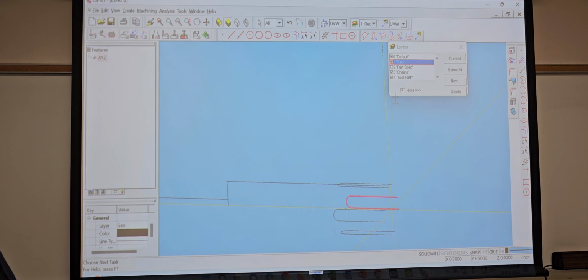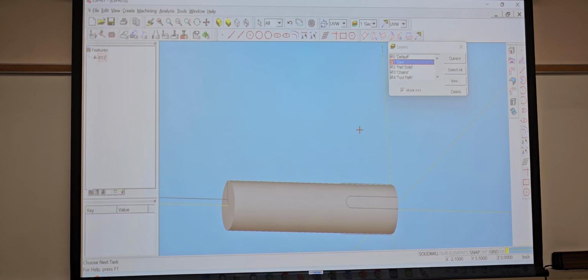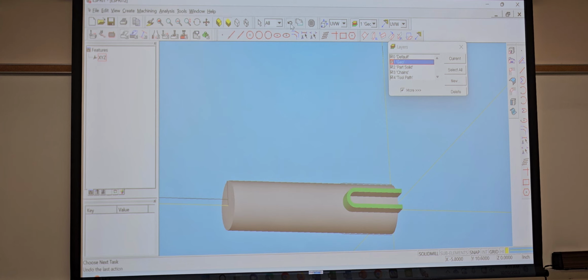So I'm gonna select this one, part, extrude cut. Oh, I hit revolve. So, click that one. Oh, look what's happening, it's a horseshoe. It's not letting me because I took off the line. Yeah, reverse. We would have to keep the line on there. No big deal.